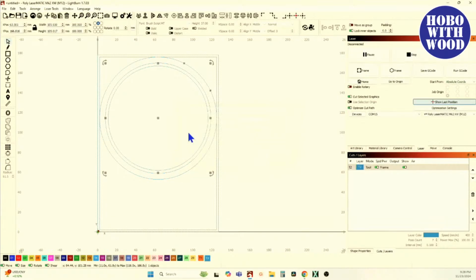Say okay. Now I'm going to come down here and draw a rectangle, and I'm going to tell it to be 25 millimeters by 6 millimeters. For y'all who are going, wait a minute, why, what, how, I won't explain all that, but I'm just going to show you real quick how easy this went together for me. So that was 25 by 6 millimeters.